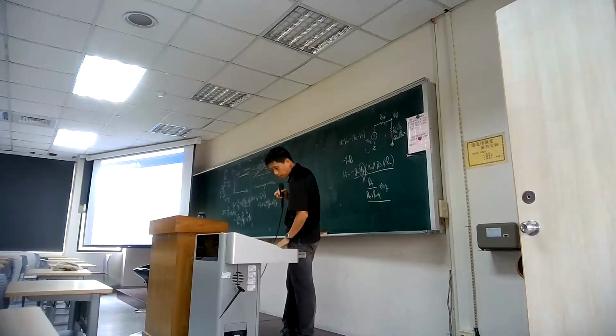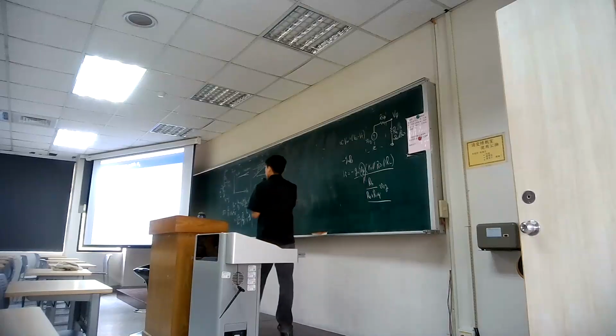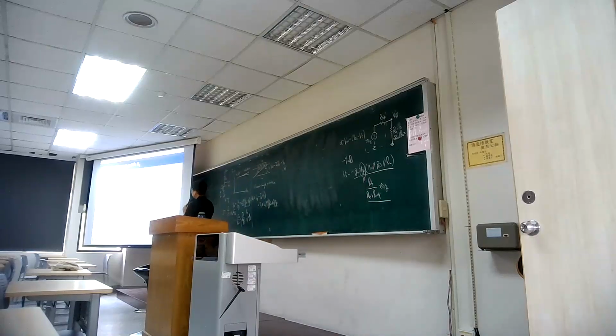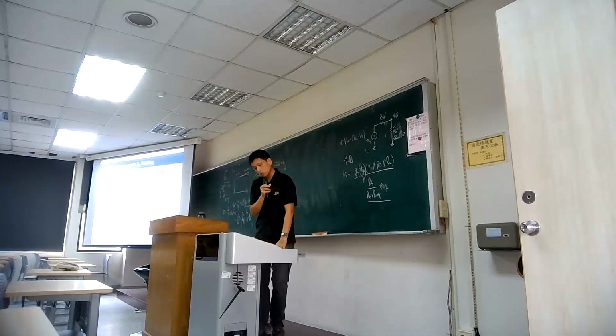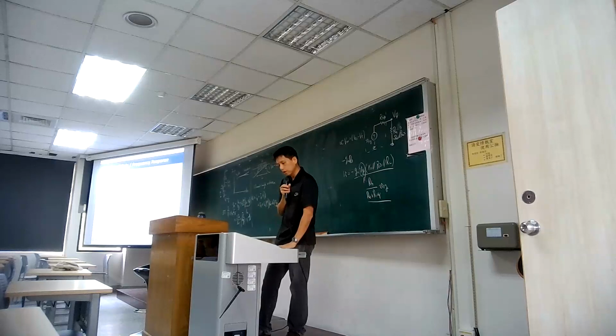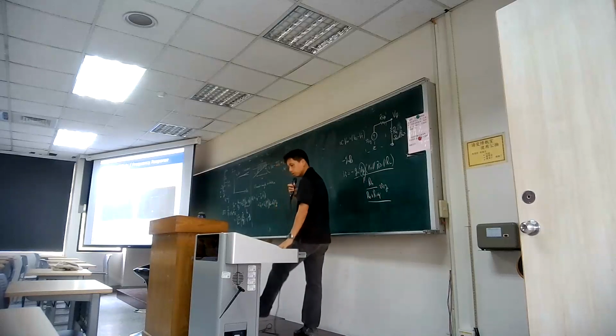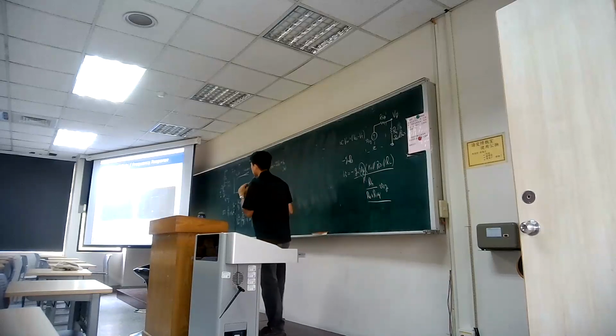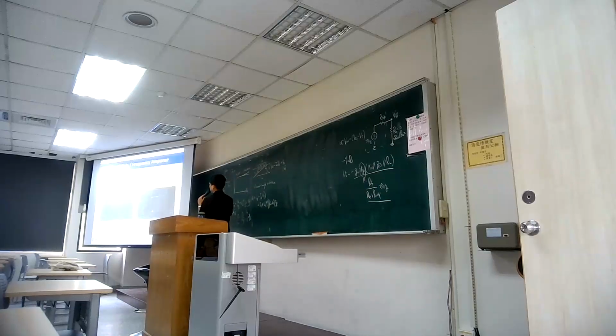Yeah, quickly show the next slide. What we get here is that we add an RS resistance on the source side. What happened here is you can see the amplification can be slightly changed. I don't want to cover that part, but you can think that if you get additional RS, the resistance at the source side, you lower your amplification.